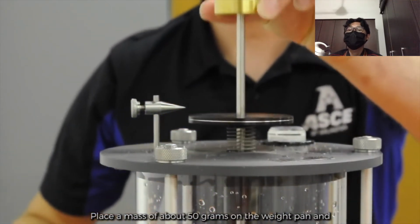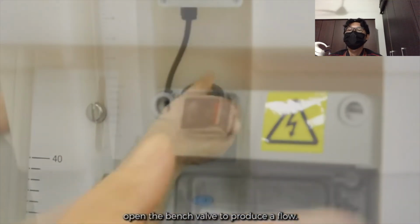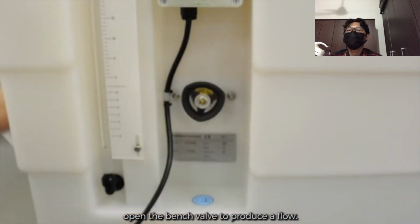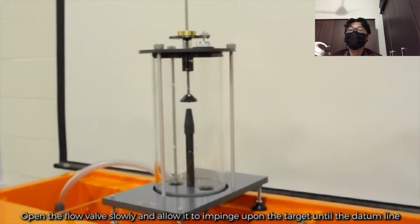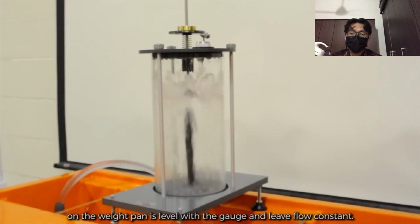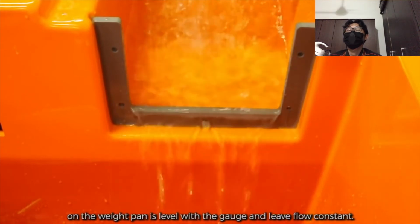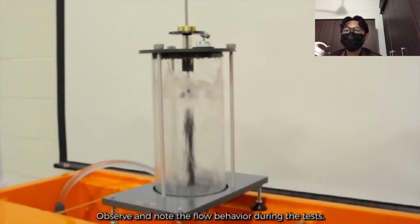Place a mass of about 50 grams on the weight pan and open the bench valve to produce a flow. Open the flow valve slowly and allow it to impinge upon the target until the datum line on the weight pan is level with the gauge, and leave the flow constant. Observe and note the flow behavior during the test.